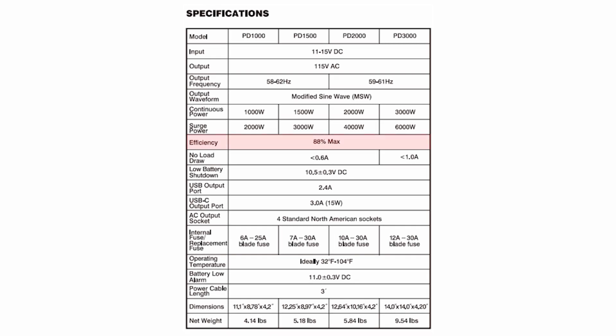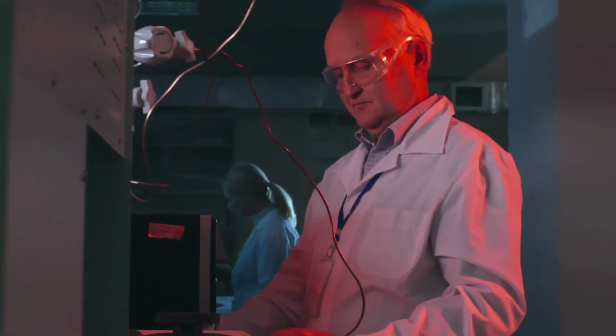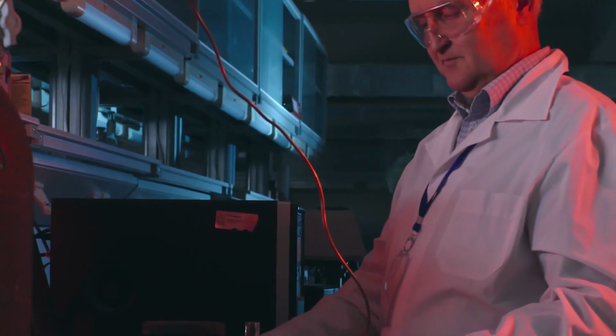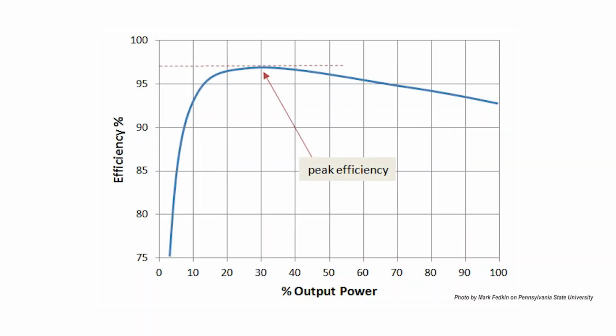In fact, the conversion efficiency indicated by the inverter is the best efficiency measured by the manufacturer in a good heat dissipation environment. Different power loads will affect the conversion efficiency. The inverter's efficiency is usually highest between 15% and 60% of the rated output power. Therefore, the inverter power will reduce the conversion efficiency when fully loaded.